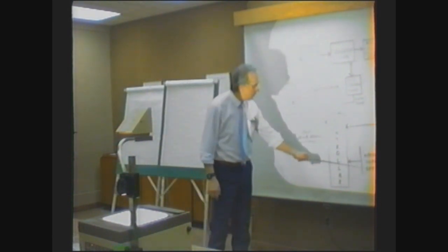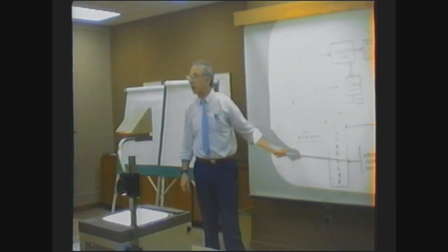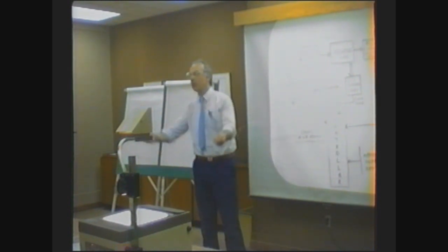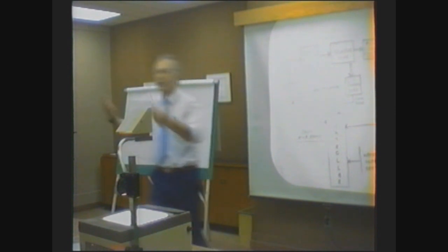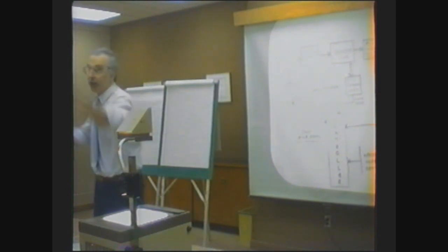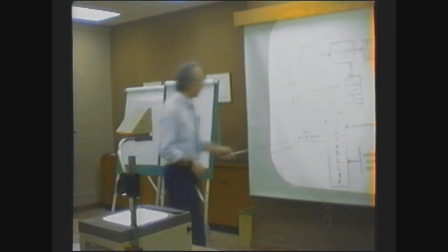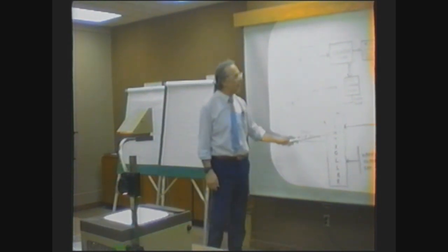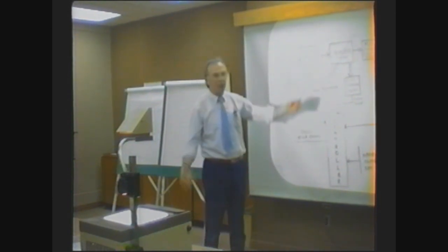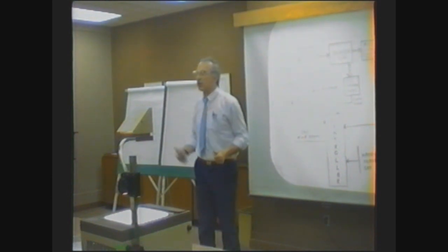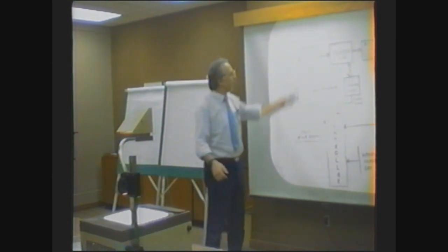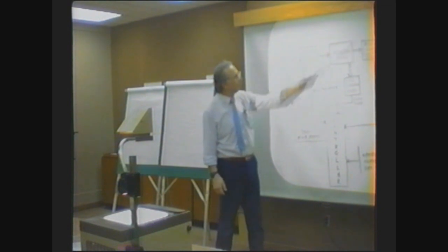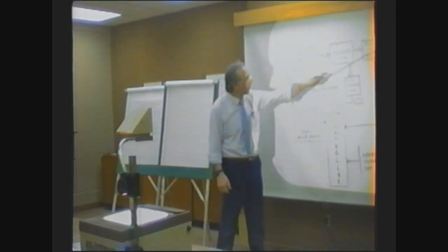The operator here communicates with the programming controller and inputs a certain demand power that he wants to set for the reactor, so many megawatts. This is an input to the controller, of course. But at the same time, there are inputs to the controller: the different process variables from the field, which are the fission chambers, which measure the neutron flux.